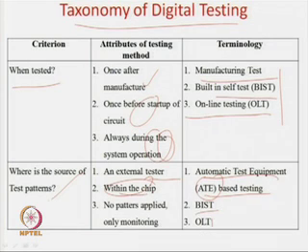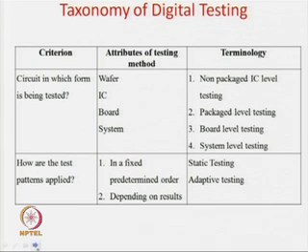And now you see what is the case of online monitoring. In online monitoring, the circuit is doing its normal operation and you are just monitoring. So, obviously in this case you cannot apply any pattern. The circuit is doing its operation, no patterns are applied, you are only monitoring and then judging whether the circuit is behaving properly or not.